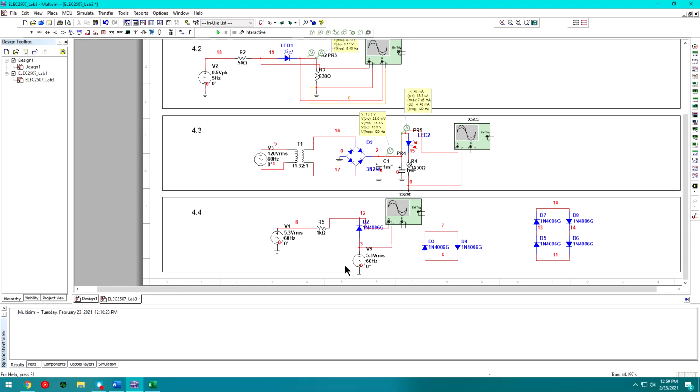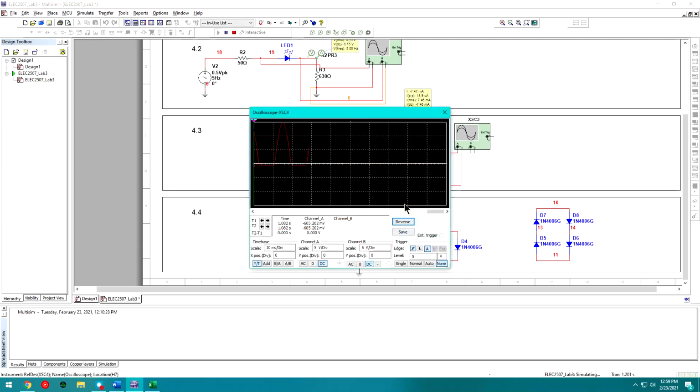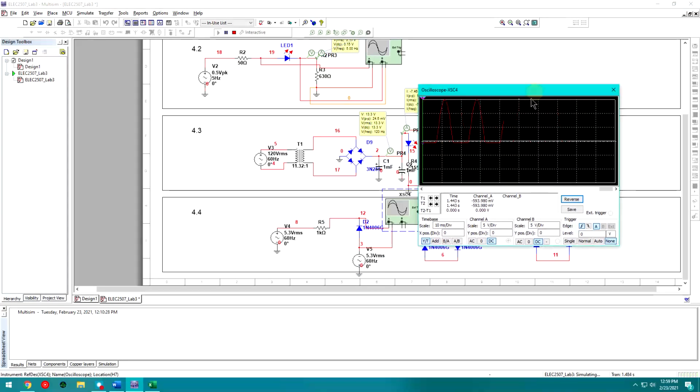All right. So actually, for this step, I've had to split the 10.6 volts RMS up into two different sources because we weren't actually getting convergence on the circuit when we were doing it the other way around. So I'll go ahead and run that simulation. And we can open up this waveform here. If we run a single sweep and go over to the waveform, we can see that this is actually just below the turn on threshold, right?